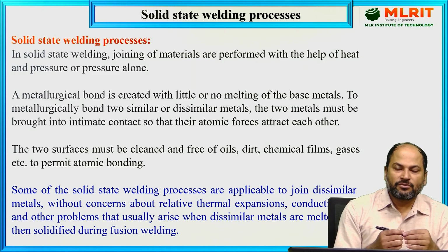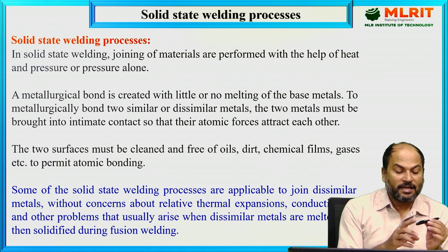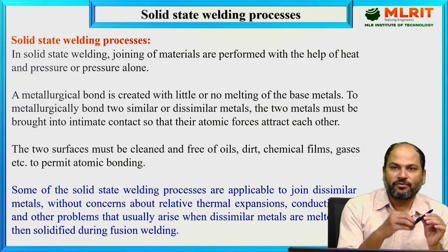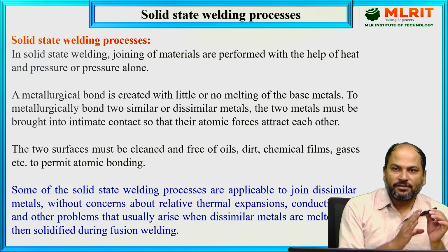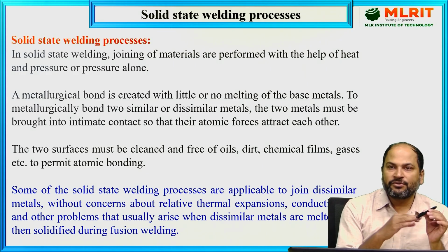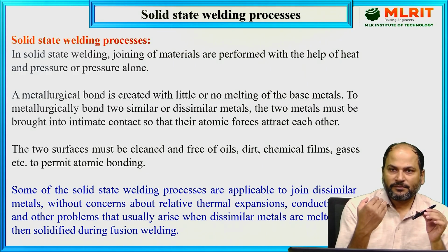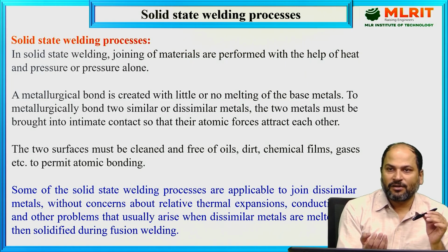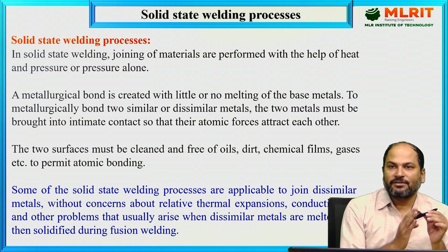What we saw, liquid state welding means, suppose I'm welding a solid part. If I have to weld these two parts, and I'm using heat or pressure to join, and the solid state of the material is not changing, meaning it is not changing to liquid state, then we say that this is a solid state welding process. But if during the welding process there is melting of the material, then it is known as liquid state welding process or fusion.